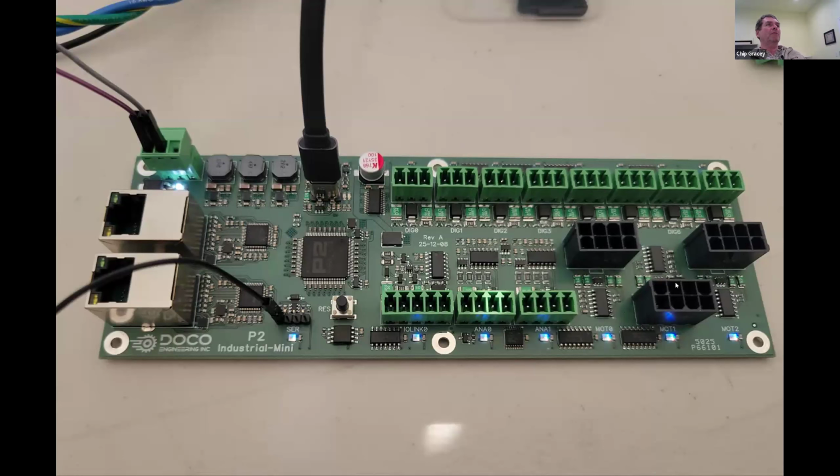So that's realized on the P2, of course, but then over these connectors, which take these, I think they're called ClearPath servos. And then down here we have 2 analog IOs that are 0 to 10 volt in and out. I'm working on the code for that at the moment. This thing here is an IO-Link. It's a 24 volt 230.4 kbaud serial system: ground, serial IO, and then 24 volts for the control load. And here's the ground for the control load.